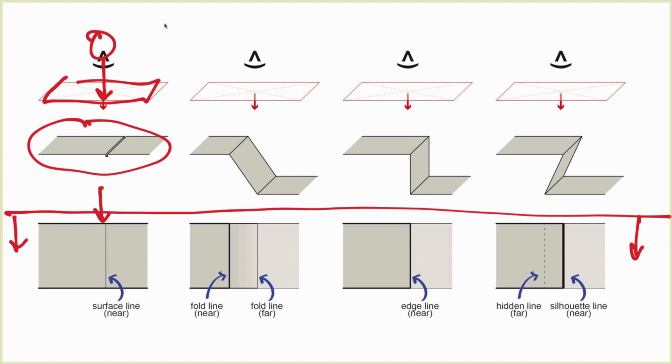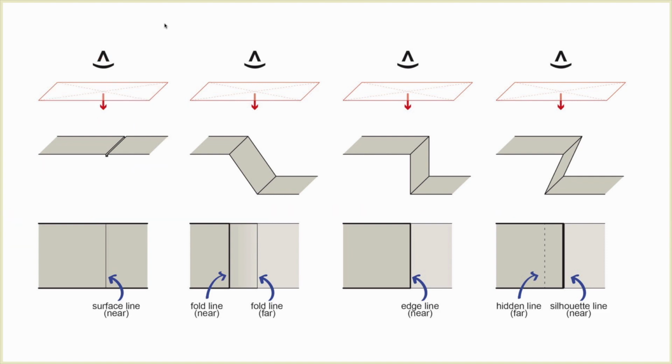As we look at the next one, drawing 2 here, this slopes down and away from us. So the boldest line is right there at the topmost edge. Then we have a thinner line right there and right there. And then we have the thinnest line of all here and here. So the further away we go, the thinner the lines become. Things that are closest to us have the thickest lines, and things that are further away have thinner lines.